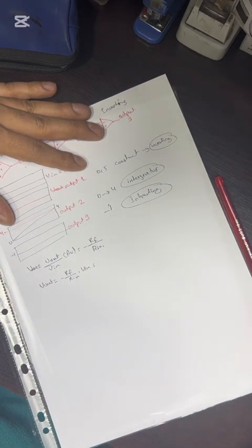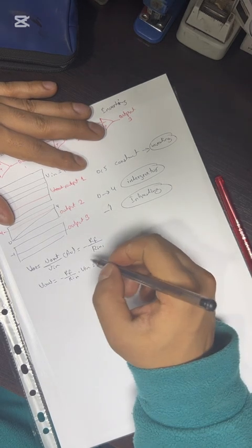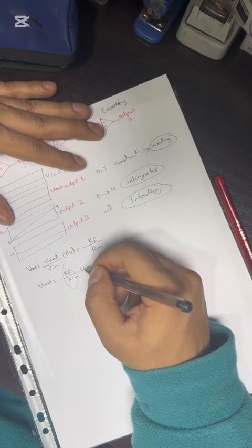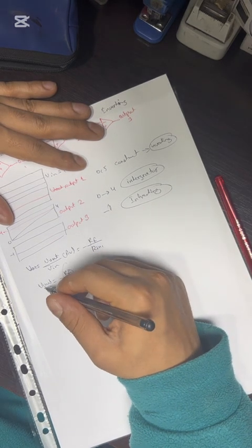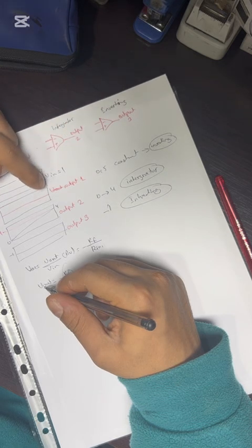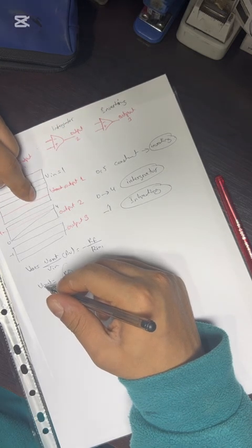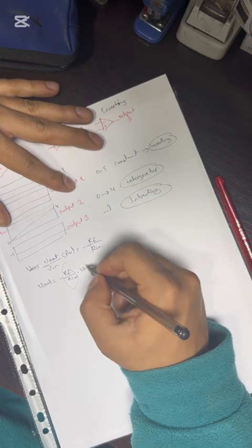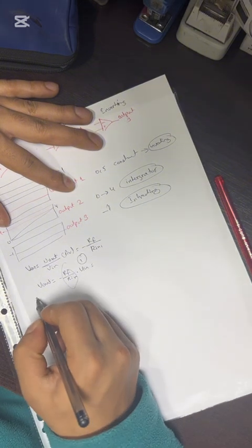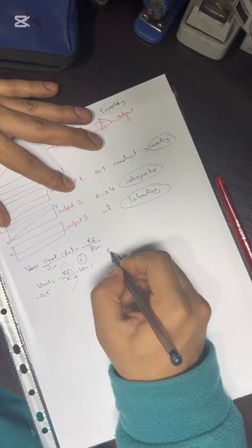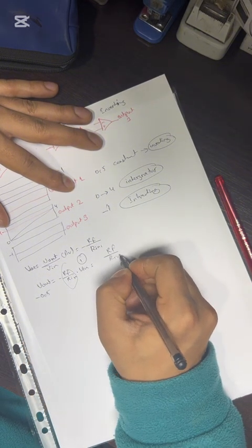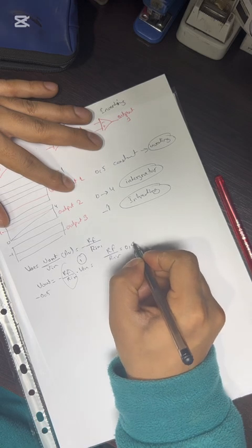So we can say, we have our output which is equal to 1 for the first one, so we can put Vin equal to 1 and our output is equal to minus 0.5, so RF over Rin is equal to 0.5.